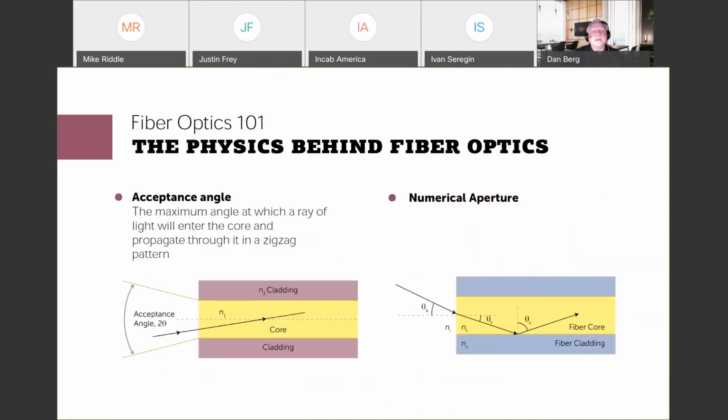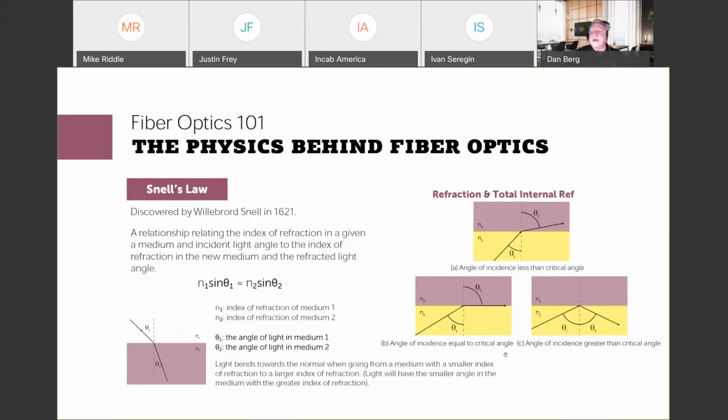And we talked about this a minute ago, the acceptance angle. The acceptance angle and the numerical aperture are, of course, related, but they really are talking about the light gathering capability of the optical fiber. This is going to tell a source manufacturer that the output of his laser or LED, most of that can vary through these angles and get light into the optical fiber. And the numerical aperture is roughly the half angle of that.